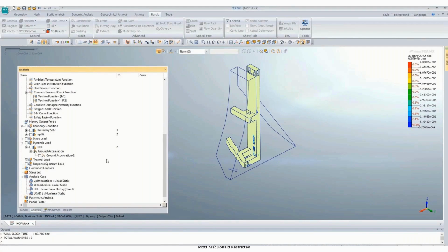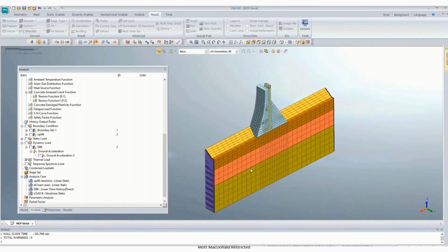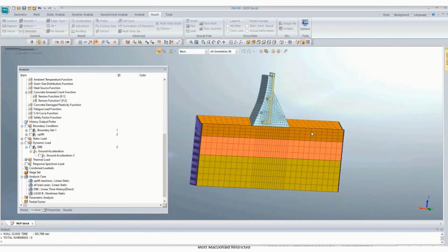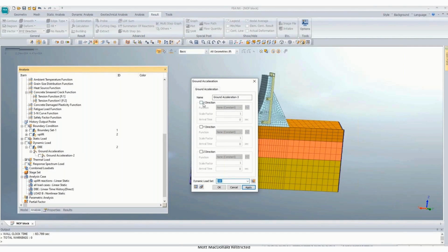Here this is a gravity structure, only some tension is there in this wall, otherwise there is no tension at all. So let's perform the ground motion time history analysis and check the stresses for that. For that, we have to again define this dynamic load case, ground acceleration x. Firstly, we'll consider, say, load case E.